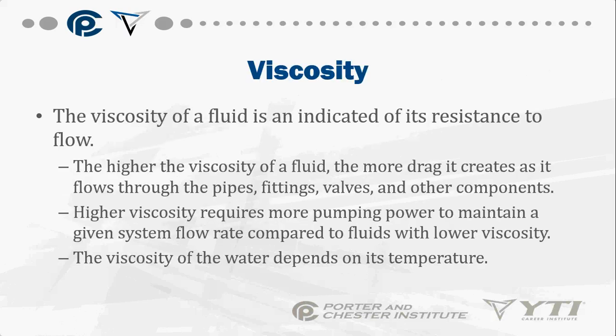Okay, viscosity, we all know what that is. Viscosity of the fluid is an indication of its resistance to flow. So the higher the viscosity of a fluid, the more drag it creates as it flows through the pipes, fittings, valves, and all the other components. Higher viscosity requires more pumping power to maintain the given system flow rates, compared to the fluid with lower viscosity.